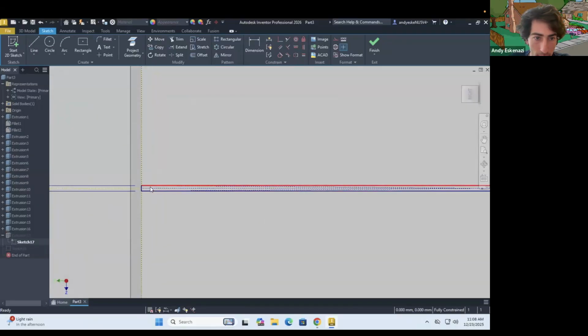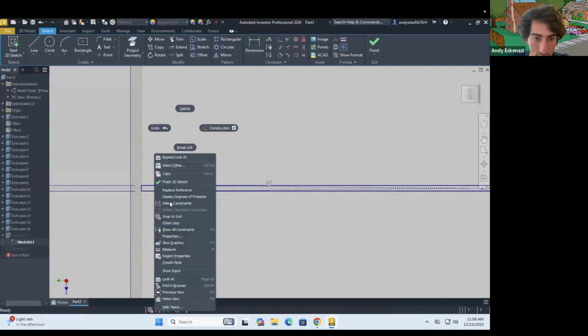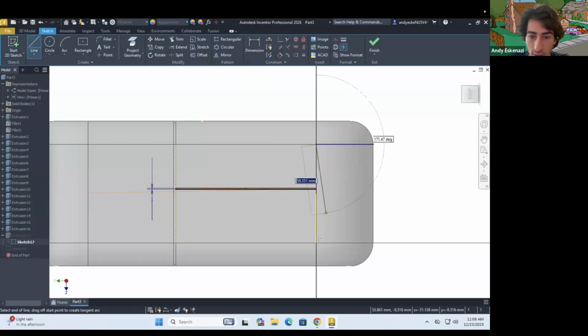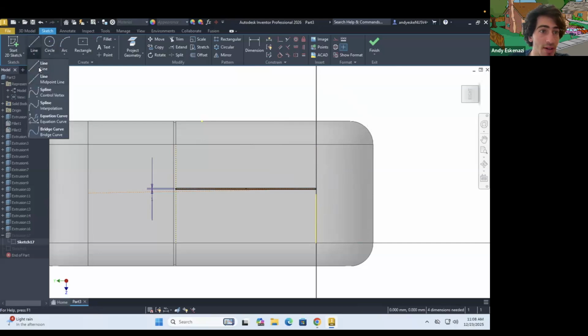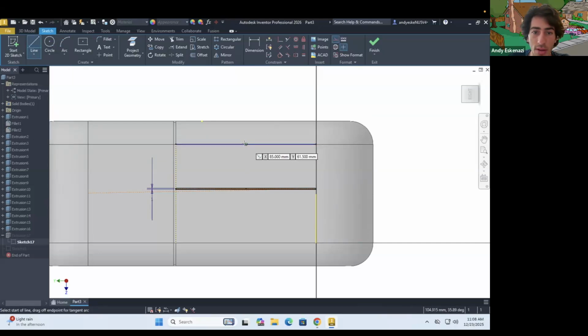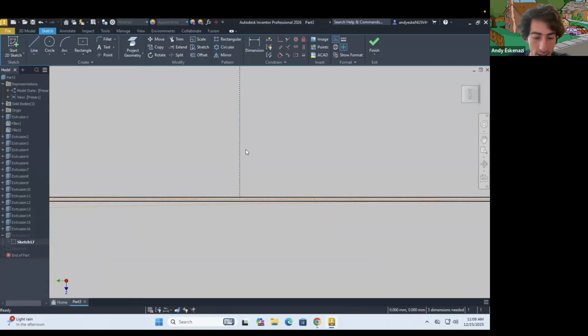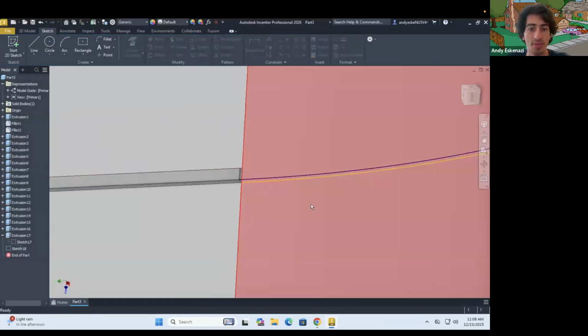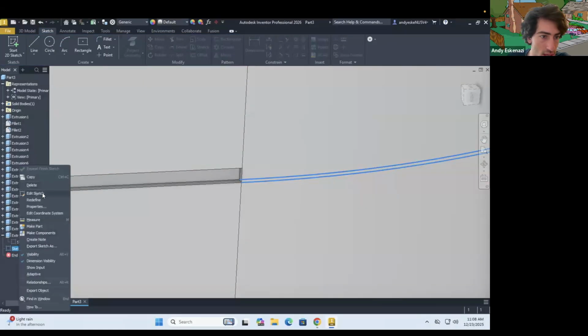Interestingly, the constraints. We know the height of this thing is 85. Huh, that's 85. So the middle point that I was marking earlier was incorrect by a little bit. I see now. So what we're gonna do is say, all right, I want that right here to be 85 over 2. There we go. So that should hopefully fix things.